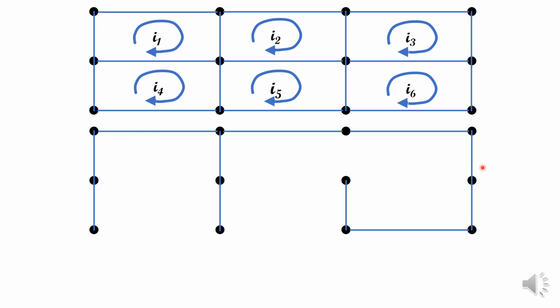In the diagram below, you have a spanning tree obtained from this circuit. It's a spanning tree because it's connected and there are no cycles. Now, for each edge that we removed to form this spanning tree, we can obtain a cycle if we add back that edge.